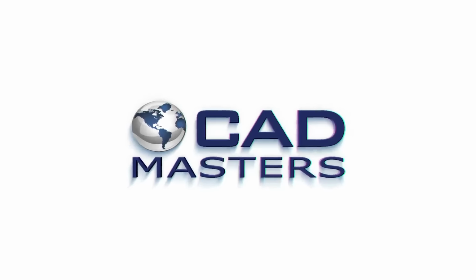In this video, you'll be watching an excerpt from our Civil 3D intro class. I'll be going over the basics of how to create a surface in Civil 3D. Creating surfaces. So we'll be creating surfaces today, tomorrow, and on day 3, but in different ways. So today, we're going to create a surface from these points. So it'll be an existing ground surface.